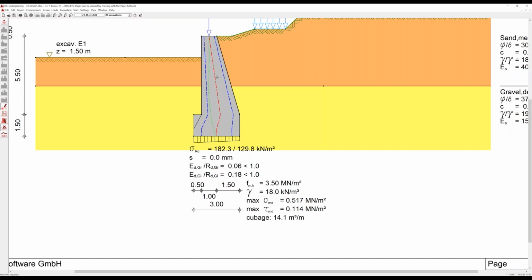And we see the thrust line where we have the load, which is transferred within the wall. And if this green line is within the blue lines, these loads can be taken by the non-reinforced wall, and we can make a design of this non-reinforced concrete.